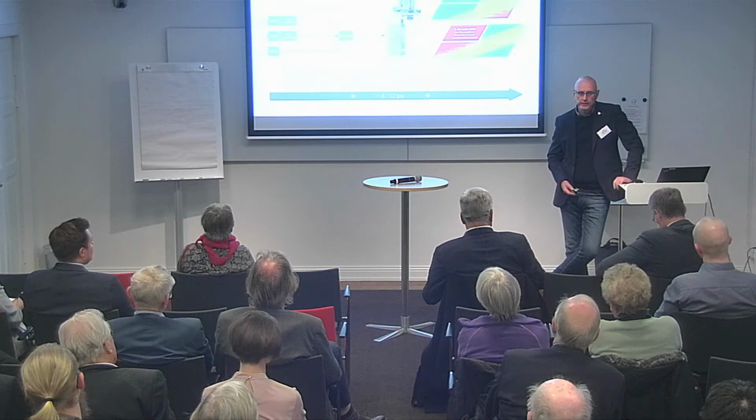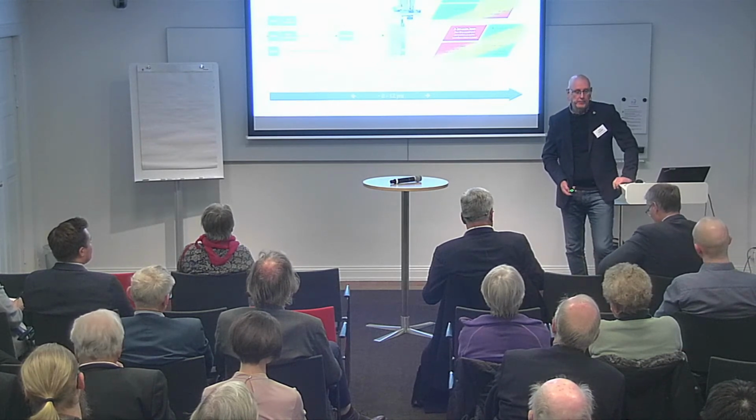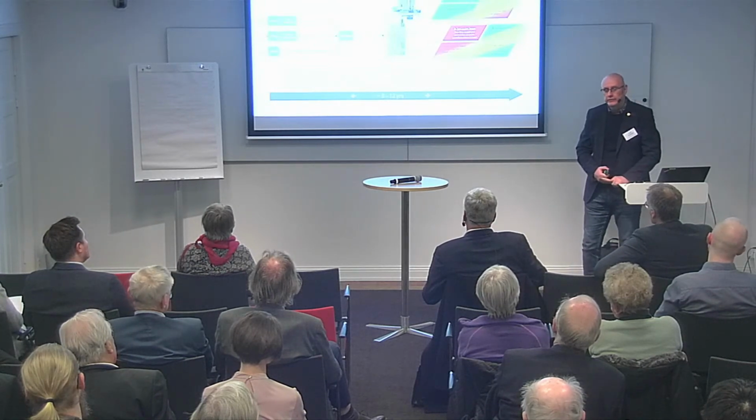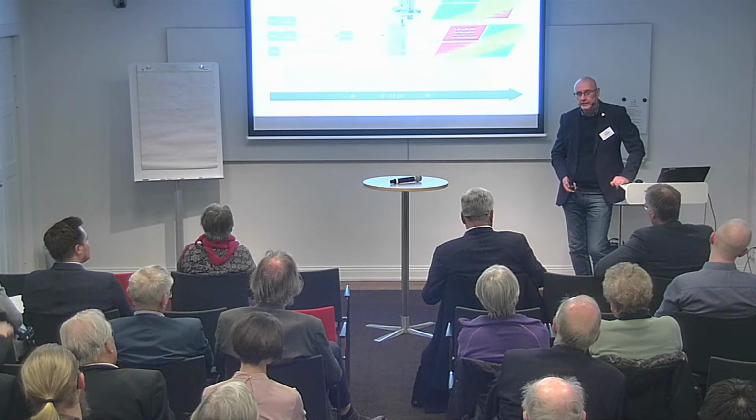There's been quite much focus on the reaction area, with examples from Stankiewicz and others on benefits of process intensification. The analogy here in the more secondary manufacturing or powder processing area, and formulated products, is the powder processing, where we transfer into continuous sets and continuous powder processing and integrate them in integrated systems. Traditional tablet manufacturing has been batch-wise for a very long period, but you can integrate them in a very small geographical footprint and then use it for much improved flexibility in your manufacturing operations.